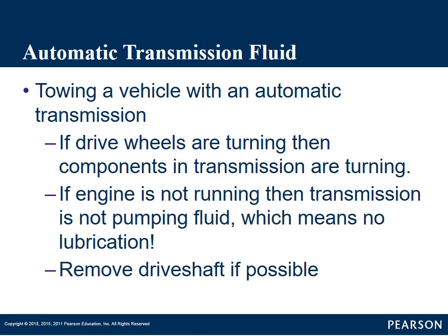Take precautions, because if you tow it over a long enough distance or fast enough speed with no lubrication, you're going to ruin components. You're going to ruin a transmission. Your best bet, if you have to tow that any distance and you cannot remove the drive shafts, is to get a tow truck. Get that towed properly. Even if you have to pay 100 or 200 bucks for a tow truck, that's a lot cheaper than 1,000 or more on a transmission.